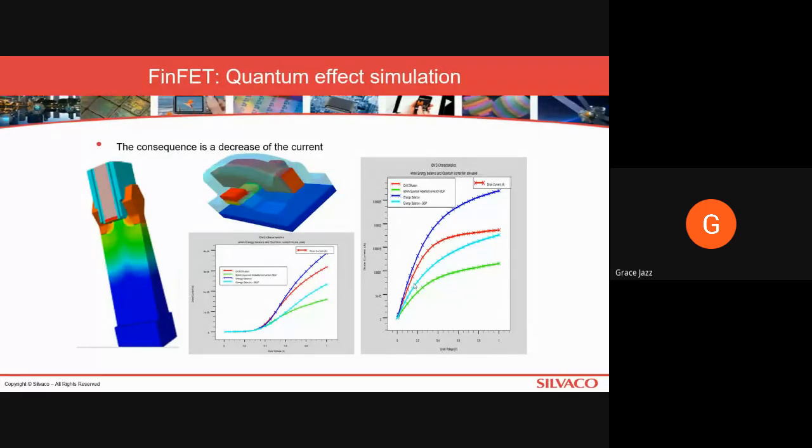We also support very advanced technology such as FinFET and FDSOI. As I introduced to you before, we support very detailed physics-based simulation. We can do very good strained SiGe epitaxy for the source/drain area. We also support very good device models such as the drift-diffusion model and energy balance model, because for smaller devices, this kind of effect is quite important.